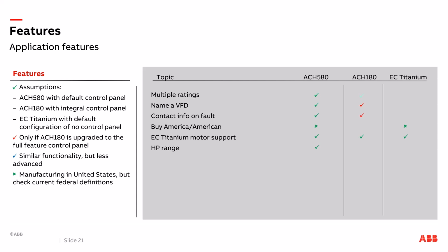Let's say I have a 10 horsepower drive, but it's only ever going to get loaded at about 75%, so really the equivalent of 7.5 horsepower. If it's only getting loaded at 75%, then I can lower my input current rating by that amount, which lets me even further reduce the wire sizes, fuse sizes, and upstream electrical protection devices.